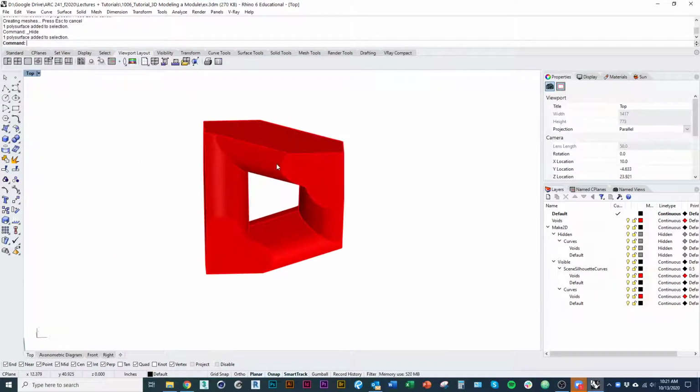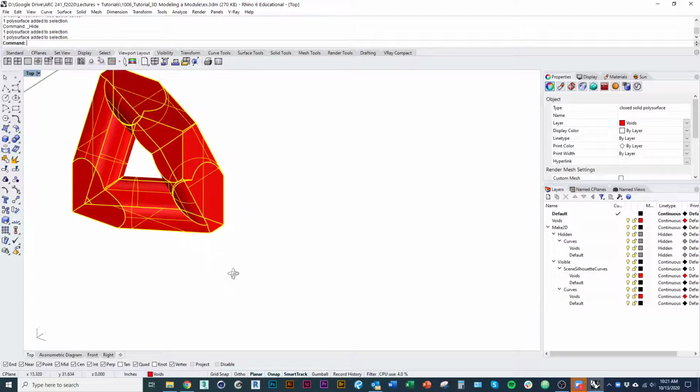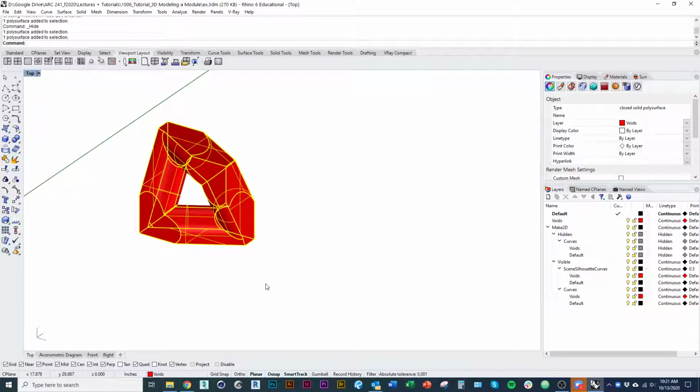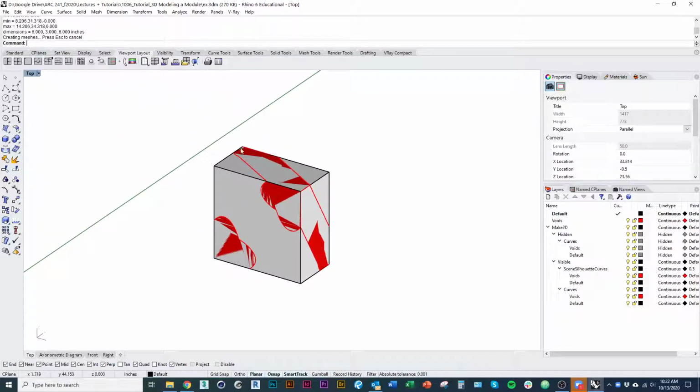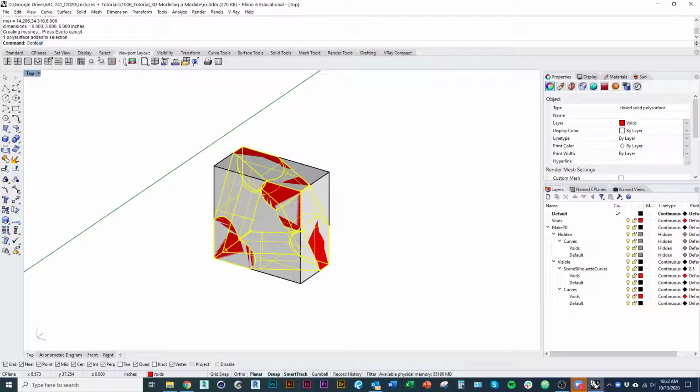So again, let's imagine we wanted to make this out of foam. We didn't want to bother figuring out how all these weird cylinder intersections happen. The other way we can do this is we can make contours. So I'm going to make a box around this form. Now this one fills the whole void, but imagine you had one that didn't. So what I can do is go, again, bounding box, which also works for 3D geometry. It'll make a box at the extents, the edges in each direction of the geometry. And then I select that and I go contour.